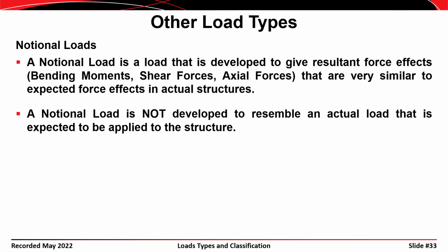There are a lot of different combinations of differential settlement that could be considered. So as an alternative to explicitly modeling this differential settlement of a foundation, many engineers will put a lateral load on the building that is small compared to wind or seismic, but that lateral load gives moments or shears or axial forces in the building that are representative of what might be expected if an actual differential settlement occurred.